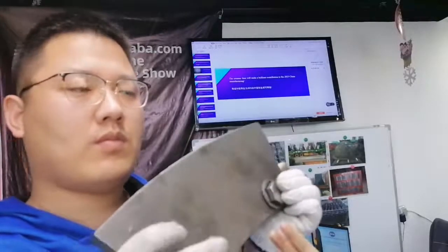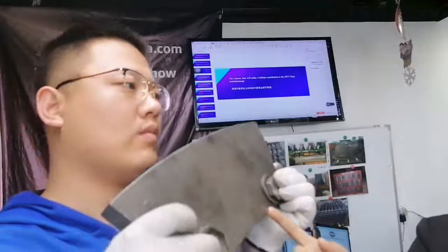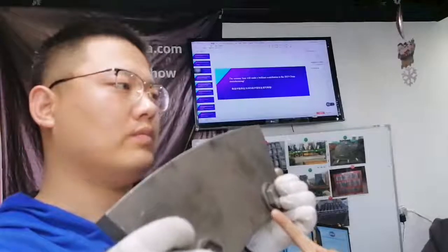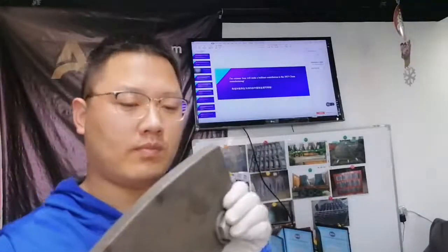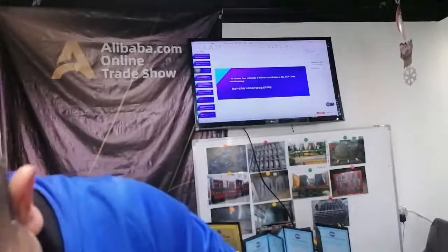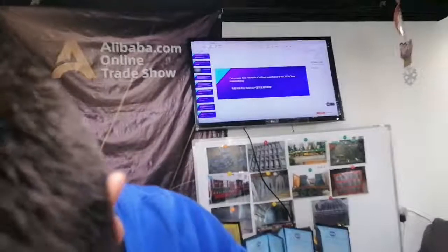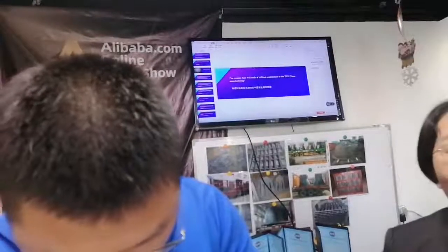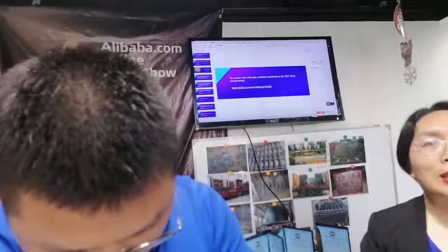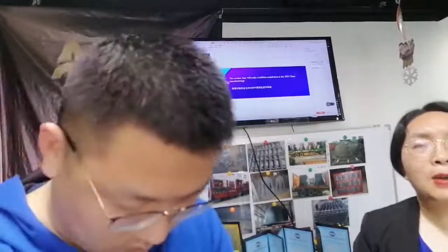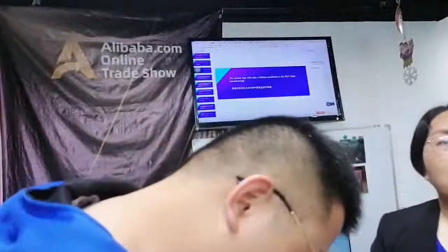So far for this part, the material grade is similar to our heat resistant steel parts. It's 2.4879 material. This is a very good heat resistant steel material, but there is no good wear performance.